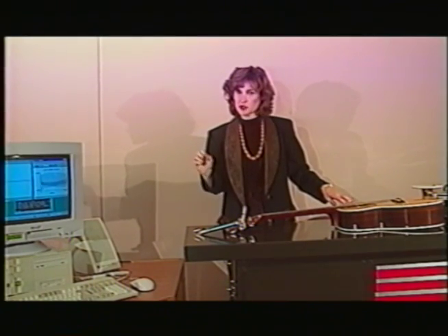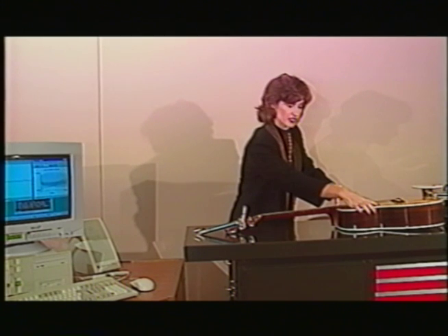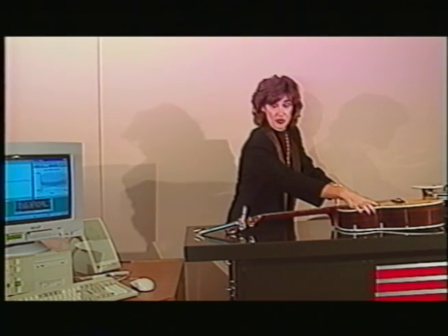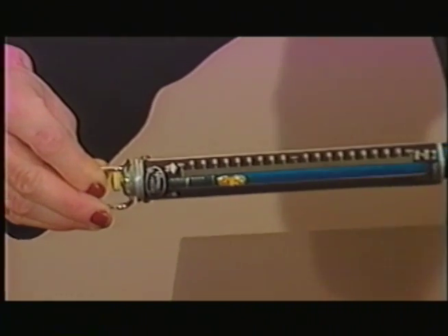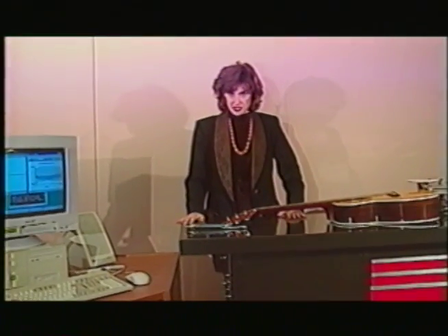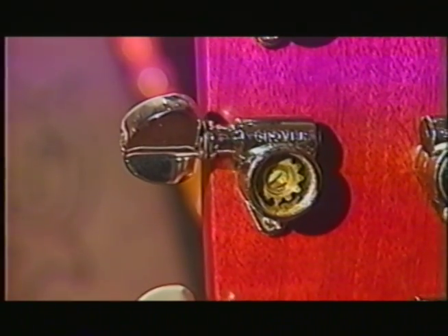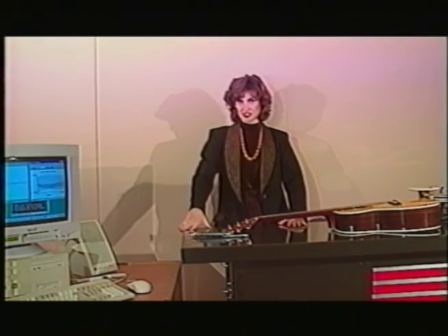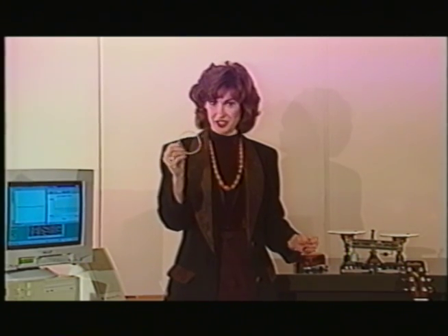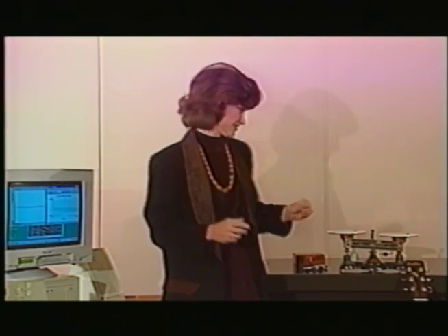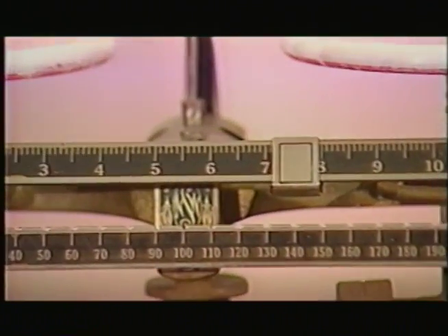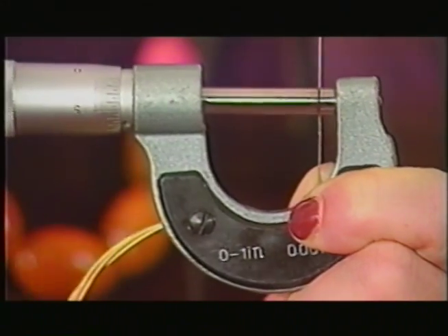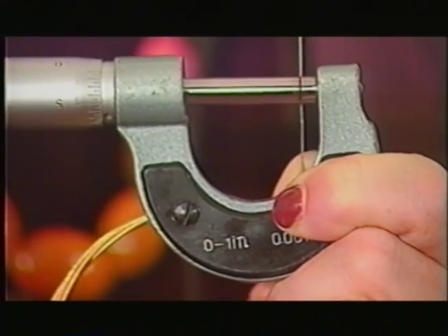First, we measure the force applied to produce this low A note, or a natural frequency of 110 cycles per second, or hertz. Multiplying the measured force with a leverage factor of 220 for the screw gives us an applied tension of 31 pounds. Then we measure and weigh the string to obtain its mass density. Also, we need to measure the cross-section area of the part of the string which will be in tension.